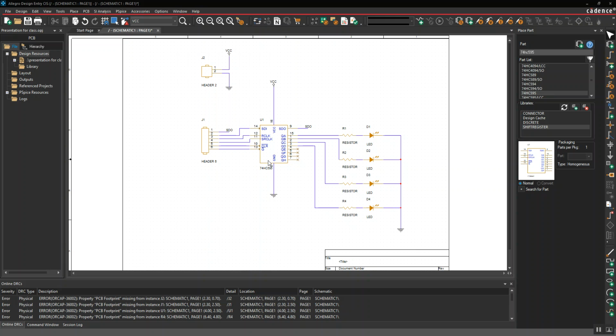When you make your custom schematic, you can move around the pins in order to make it flow better. So all these are the outputs, but you see how all these would be on one side and then this would be on the other side of the board. You want to make sure that when you make the footprint or you assign one, that it's laid out the same way you would on a data sheet.